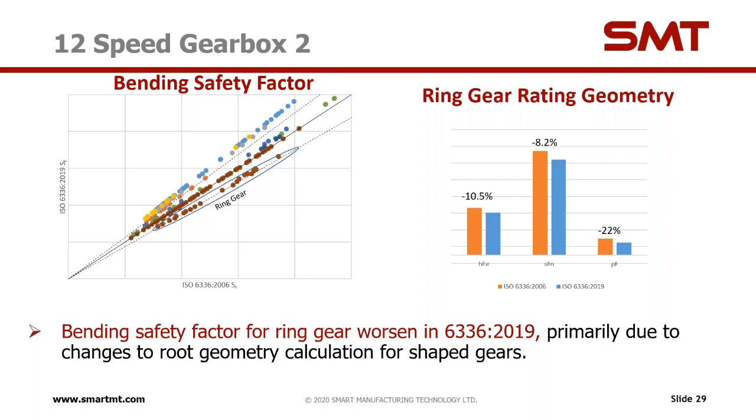Also, it was probably worth mentioning that if you were using cutters in design mode or the manufacturing mode in MASTA, these values are actually calculated based on the geometry rather than using the equations in the standard.